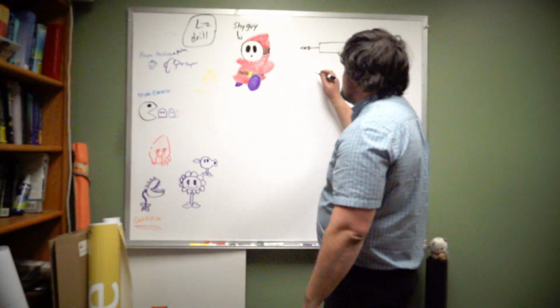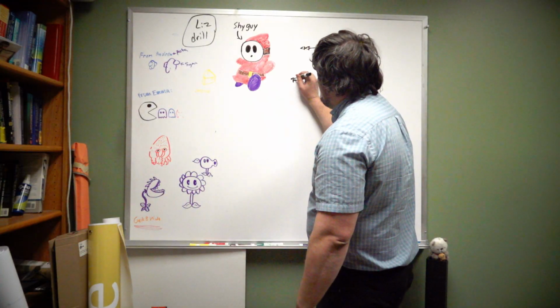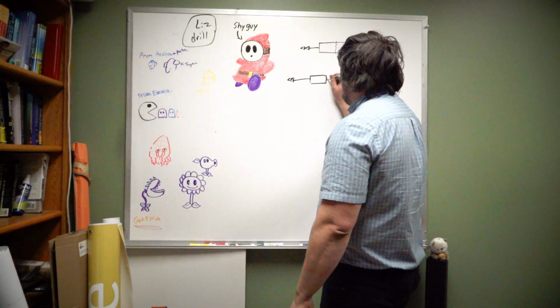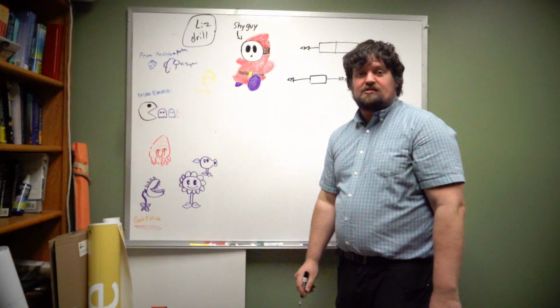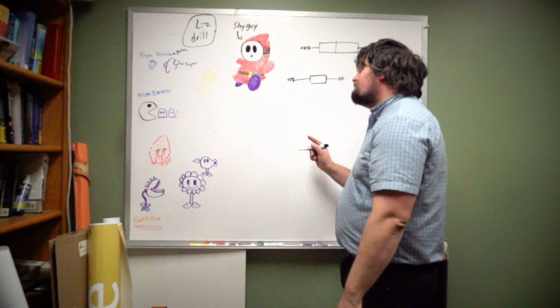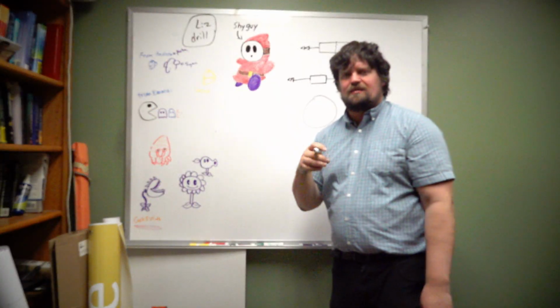But when we're looking at this, if we go ahead and break this again at this interface, you have your torsion over here, you have this piece, and then this has to carry a net torsion, which is equal to that, in order for this to work. Now that net torsion has to be carried along that face and has to be carried along the intermolecular bonds on that face. So we do run into a little bit of a difficulty here because, again, intermolecular bonds are not capable of producing a moment.